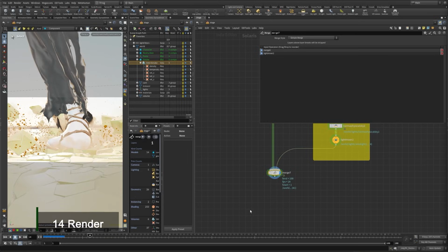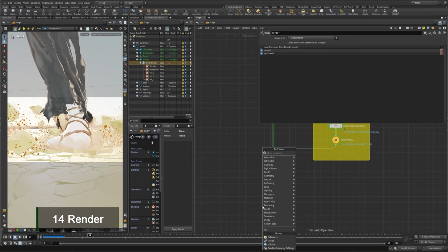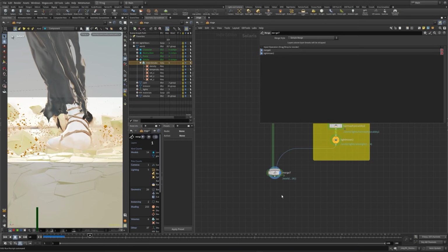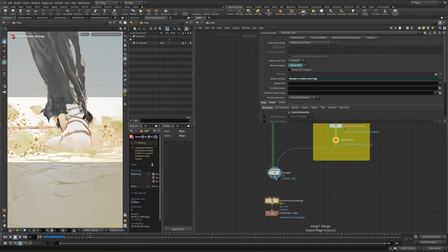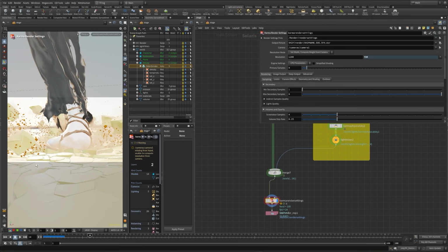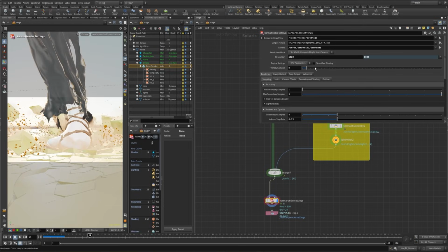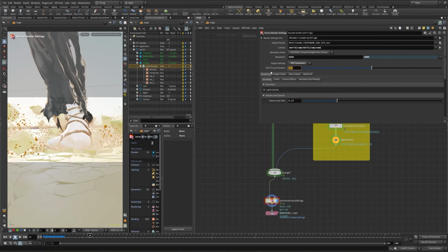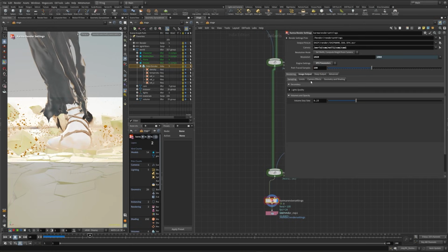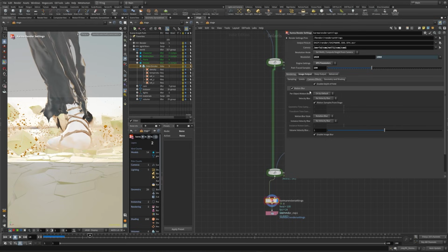Now we will move to the last part, the rendering. So for this, we're using a camera node. I will just do a really simple setup here, so you just understand how you get out. So we're using Full HD, selecting our camera. I want to use XPU, maybe 100 samples. Into the image output, we're using a filter. I'm using the Intel one. Inside the rendering, also under cameras, under the motion blur, we need velocity blur in here for the smoke.